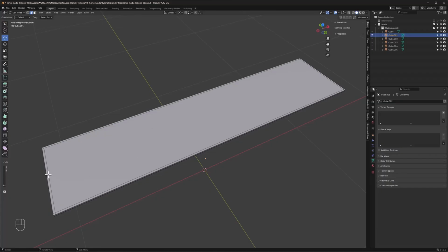Instead of selecting the lines that define the loop cuts one by one, we can make this operation much simpler and faster. Hold down the Alt key while left-clicking on the first loop cut, for example, the one on the short left side of the panel. This way, the entire loop cut will be selected in one go. While holding down Alt, also press the Shift key and, still using the left mouse button, select the other 3 loop cuts.